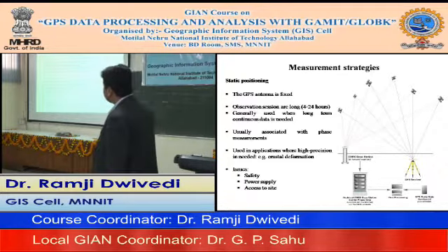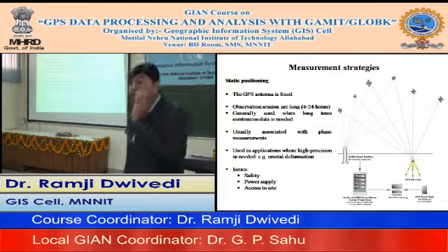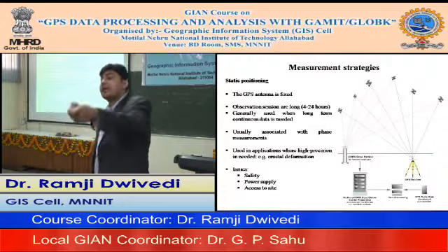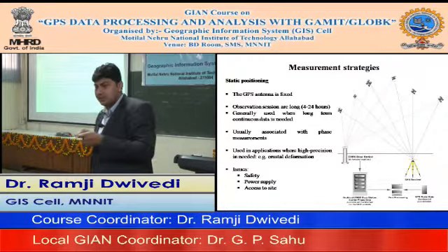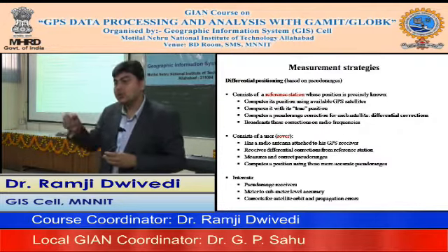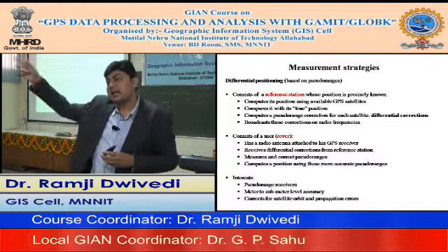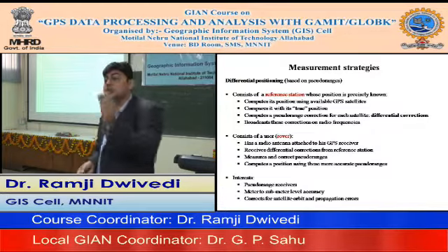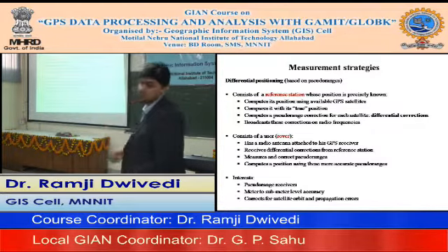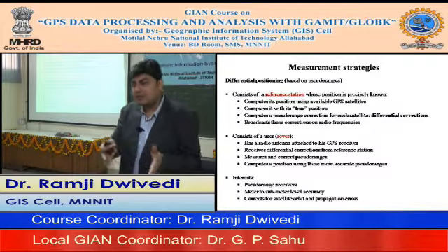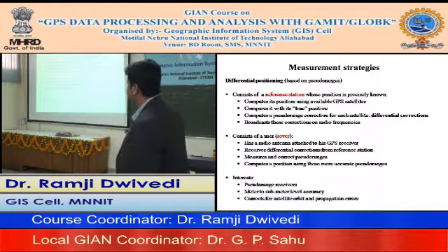Similarly, the differential positioning, as I said, the word DGPS comes from the fact that you are using corrections to the pseudo ranges. Please remember, DGPS is the differential GPS, but in this case you are taking the corrections which are estimated at the base end, but you are applying them at the rover end. So corrections to the pseudo ranges become the concept of DGPS. However, in the relative case you are working with the prime observables of the carrier phases. So this is one difference of the nomenclature. However, nowadays people are using them interchangeably.